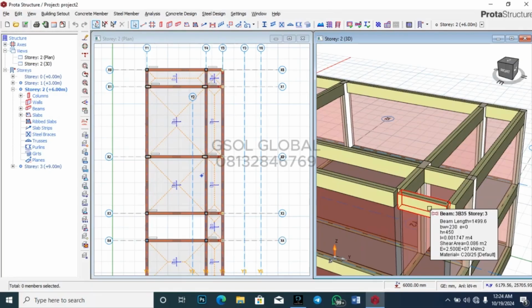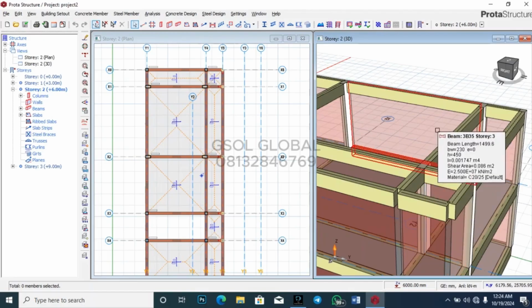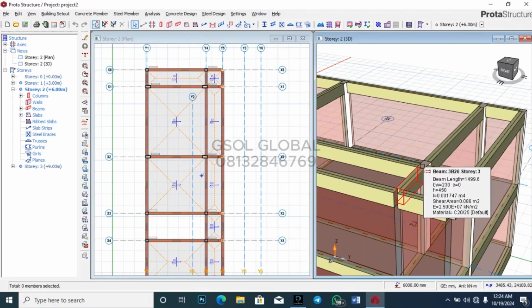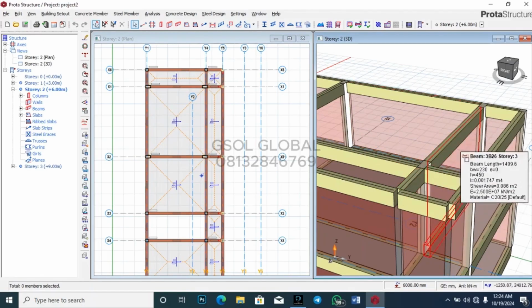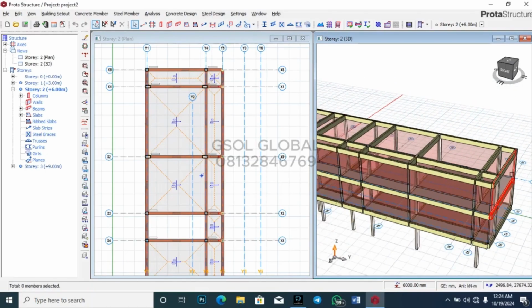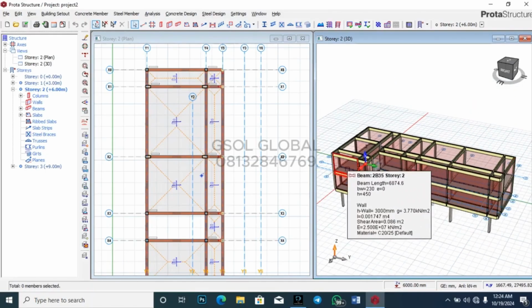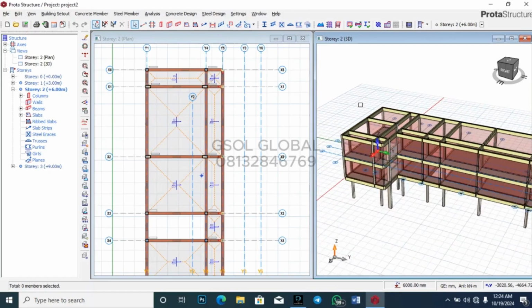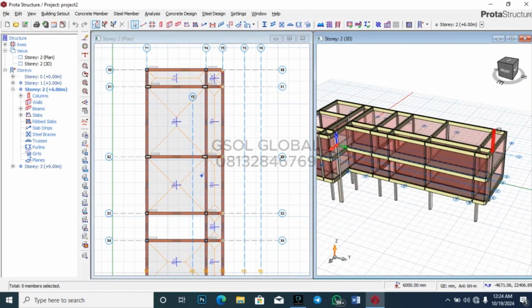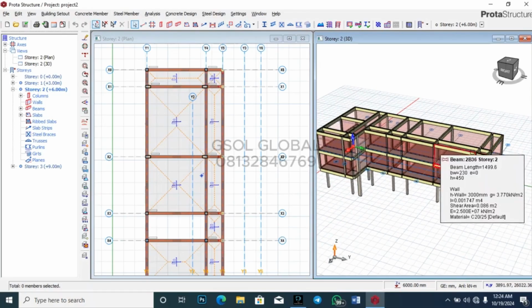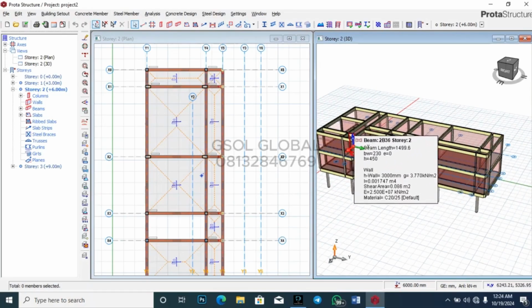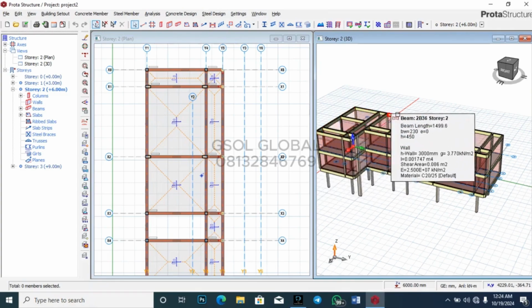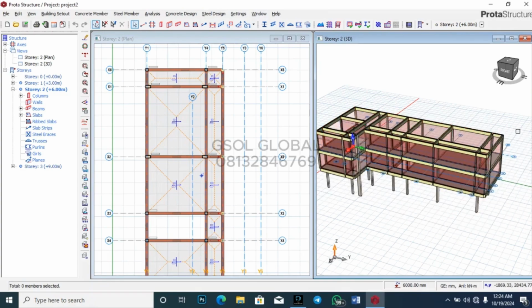From the 3D view, you will see that there was a short wall on each of the beams, but majorly it is at the surrounding. That's the beam at the circumference. That's the beam around the circumference of the roof structure. This roof layout you see here now, around the circumference, you are having a short wall on them. But what we're going to do is place a short wall on all the roof layout beams.